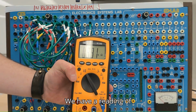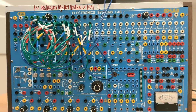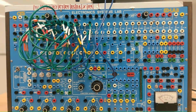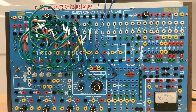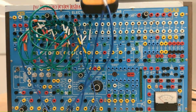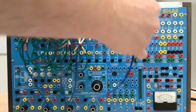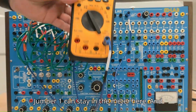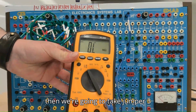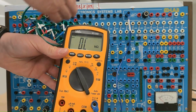We have a reading of 9.91 kiloohms. Next, we're going to measure R1, R2. So we're going to go ahead and put jumper 13 back. Jumper 1 can stay in the meter here. And then we're going to take jumper 3 off of resistor 3.